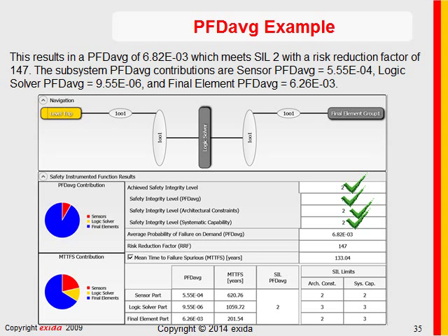I'm a little confused. Why would the PFD's architecture constraints? Let's look. Architecture constraints: a logic solver with SIL 3, a single sensor, and a single remote actuated valve met SIL 2. Systematic capability, we were limited by the sensor, which met only SIL 2. The logic solver and the remote actuated valve met SIL 3.